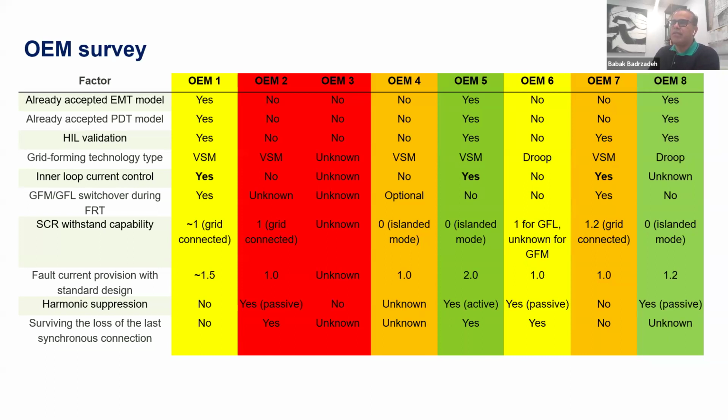Definitely, that's expected, obviously, for every design, but it's not 0, it's not even 1. It varies depending on design, and it varies depending on the control system tuning that you can achieve, like 1, which is the best under interconnected conditions, but that would likely come at the expense of not being able to meet some of the statutory or grid code requirements. Fault current, I already mentioned. It's very rare to have high fault currents, and what we have looked at also, it does not necessarily come as a significant differentiator from a system stability perspective.